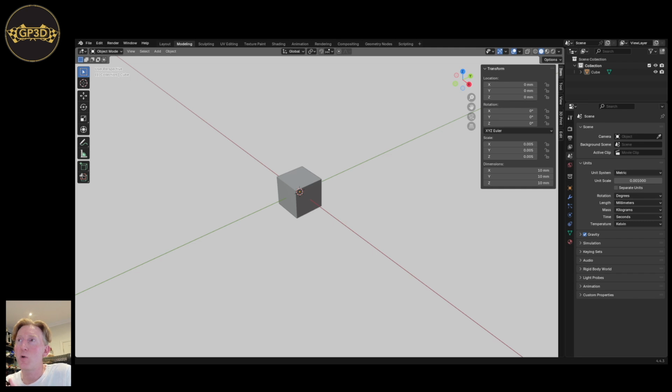So the way I do this non-destructive designing is that I'll have these core objects like a cube, cylinders, etc., that either add or subtract from each other. So that's your Boolean operator. And a lot of what I'll show you to design this will be Boolean operators. Very powerful. You can have a Boolean operator which is additive, called union.